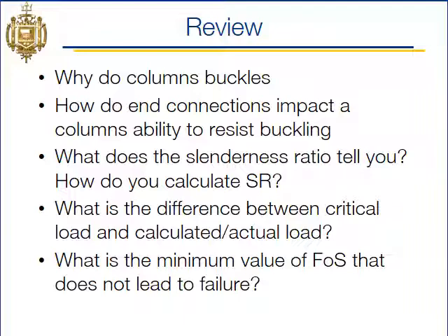So we always want to make our column stronger than it needs to be so that it doesn't fail. And what is the minimum factor of safety that does not lead to failure? And that is 1, right? If we calculate a value of 1 or greater, it's not going to fail. Less than 1, it will definitely fail.